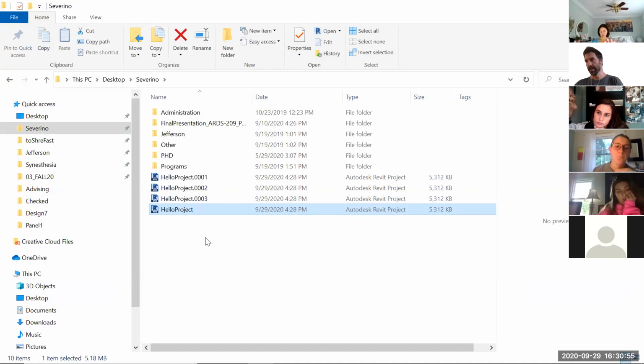Don't use symbols and stuff like that. So be as clear as possible. Normally names in the digital world are great with underscores as separators, or space as separator, but not symbols, okay? And definitely not points, because for a computer, the point means, hey, are you going to put an extension after, like RVT, which is the extension of Revit, or DWG, which is the extension of AutoCAD. That's what the point normally means for a computer. So don't use points and symbols and so on.